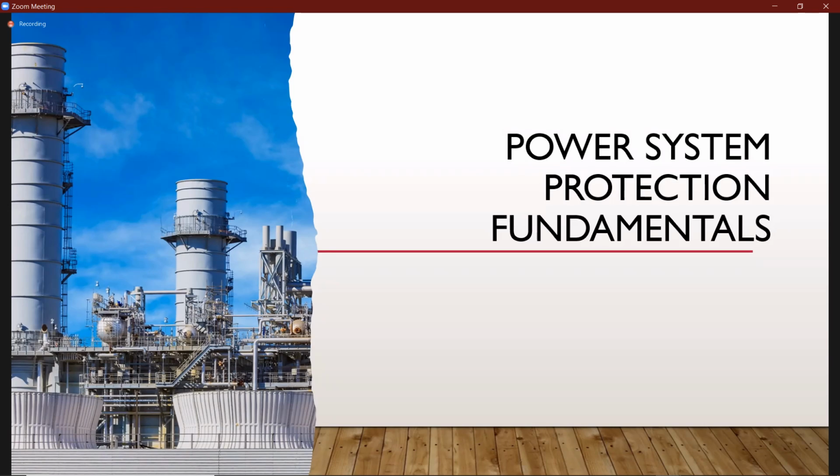So, in terms of the objectives, one, the fault is more severe at the bus bars. Earthing impedance reduces your fault current. Star delta transformers sectionalize your networks, and most persons went through the whole business of ensuring that zero sequence current can't flow with the delta or the star. I was disappointed that many persons were still just talking about star instead of grounded star. But enough individuals mentioned the fact that it's a grounded star, so I was comfortable with that.